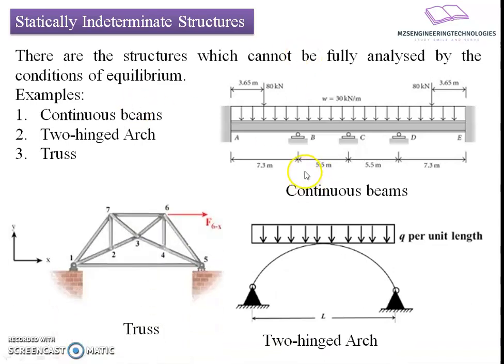In the case of a continuous beam, we have n number of supporting spans developing n number of reactions, which can't be analyzed with reference to the available static equilibrium conditions, with reference to the geometry as well as the loading condition. Thereby, unknown forces remain, which we have to analyze by developing an additional equation, either in terms of compatibility or with reference to constitutive relationships.